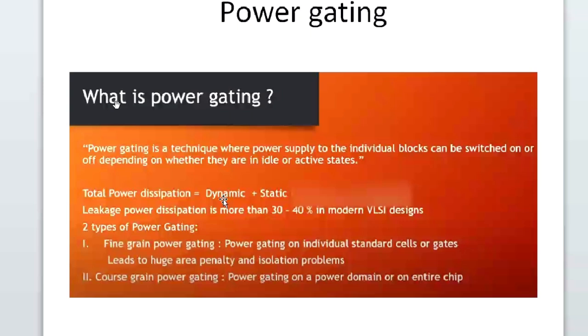Let's say dynamic power is half C V squared, where V is the VDD supply voltage squared. In a multi-voltage domain, multi-VDD helps to reduce the dynamic power. Let's consider one VDD of 1.1 volt and one VDD of 0.8 volt. The equation is half C V squared into F into activity factor. What does activity factor mean? Activity factor is the average rate of switching of the signal.